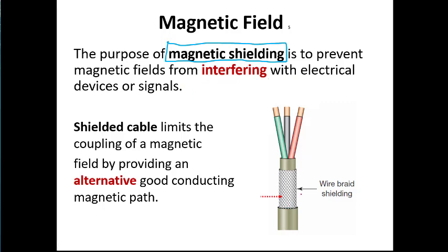You might see this if you had an amplifier in your car for a speaker system. You might have some pretty elaborate magnetic shielding devices in the circuits. A lot of times these wires will have wire braiding and then aluminum foil on the inside of the wire in order to limit the effects of the magnetic fields.